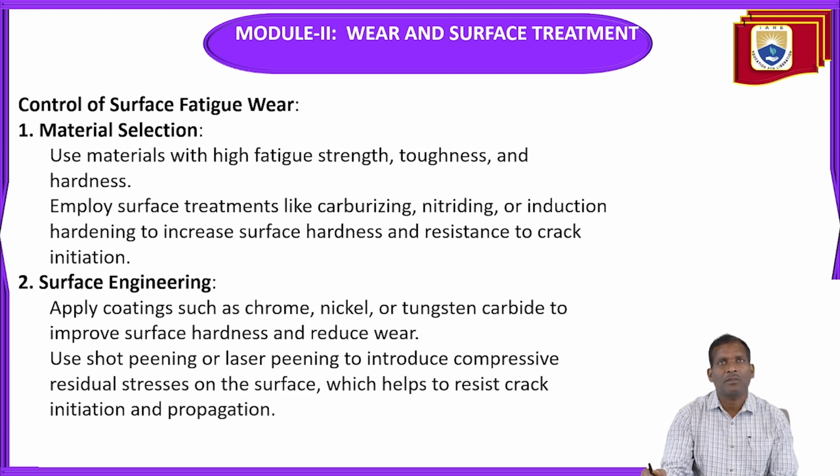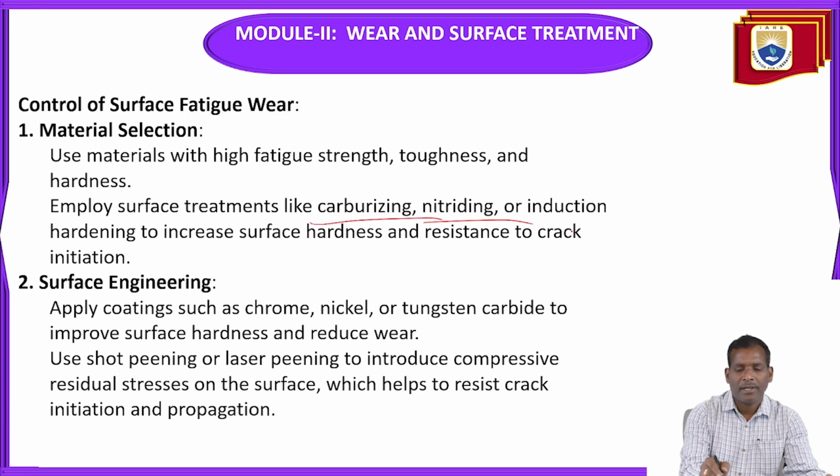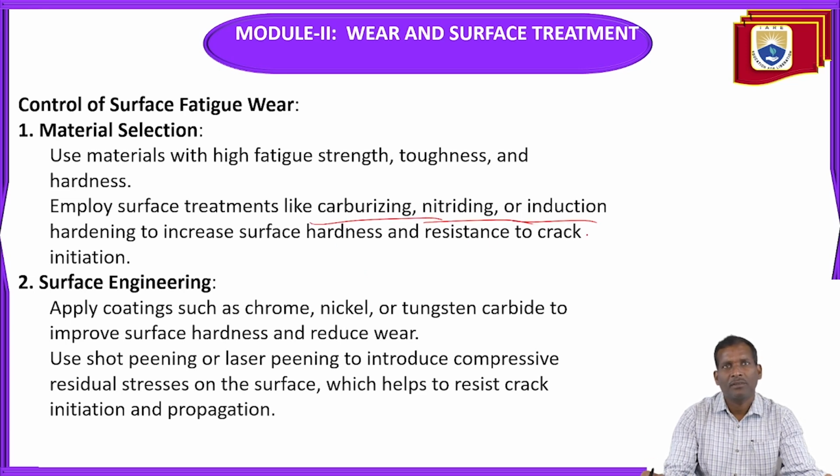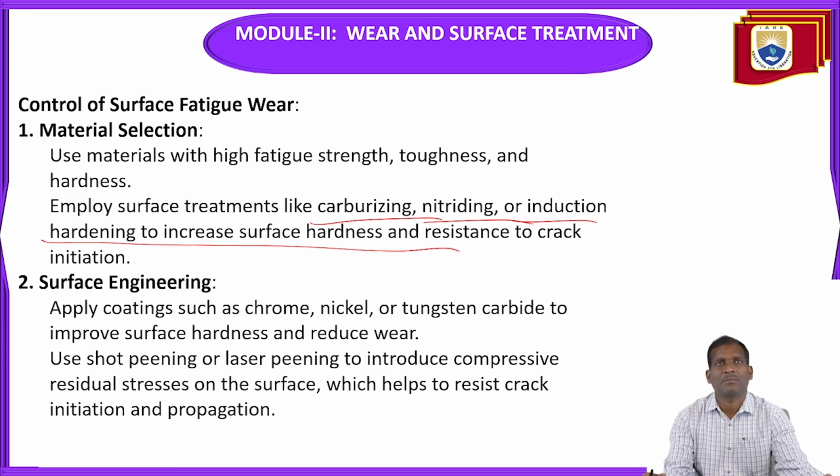The control of surface fatigue wear: one is material selection. The proper selection of material gives a long life to the component. That's why the selection of material is very important in designing. Use materials with high fatigue strength, toughness and hardness. Employ surface treatments like carburizing, nitriding or induction hardening to increase surface hardness and resistance to crack initiation.